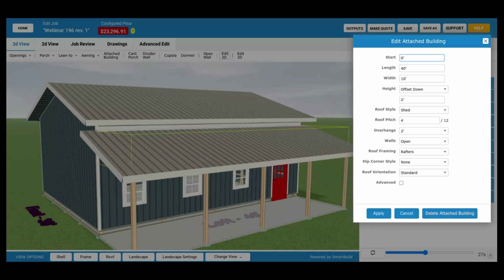So would that work with a gable? The corner lap would go. That work with a gable versus a mono roof? It would, because on a gable you're going to have a ridge cap at the top. On a mono you're going to have a high eave. Yeah, the high eave trim, which is a different trim. So yes, that trim would then allow you to control it separately.